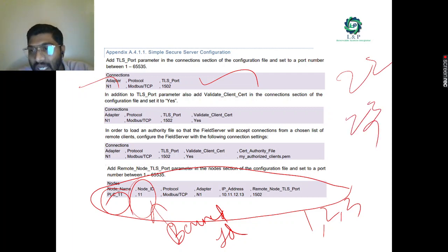These information you need to get, and you need to inform the concerned persons who are the owner of that concerned equipment. They need to assign this information inside this controller. Then only you will be able to assign. I'm not saying only the BACnet IDs. Apart from it, there is a possibility for IP addresses to get assigned there. So not only the BACnet equipments which are going to act as a slave, you can connect with the normal equipments also with IP addresses. Through the networks you can establish the communication with them, and you can read this information, extracting the information from the field.